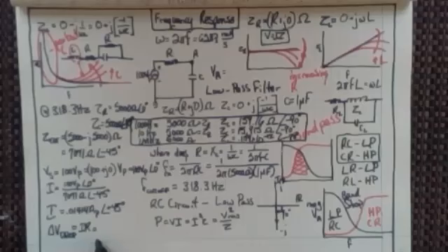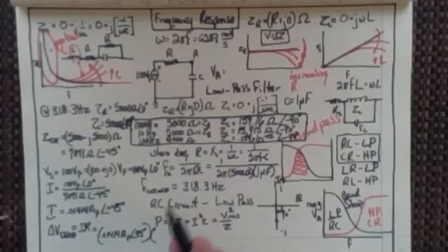So for I have 0.01414 amps peak at 45 degrees. There's my current. And then I want to multiply that by the resistance. And of course, the impedance for that resistor is just going to be 5,000 ohms at an angle of 0 degrees.